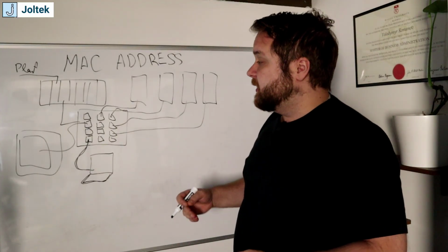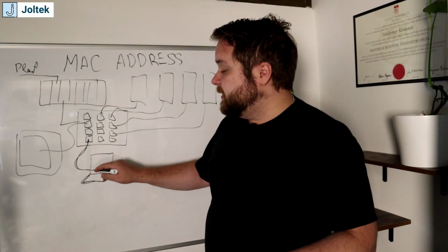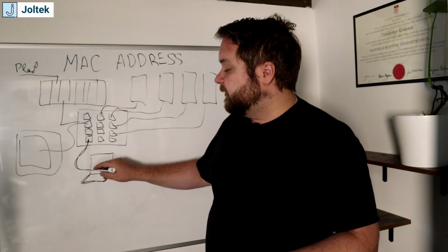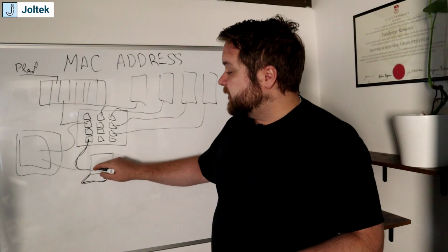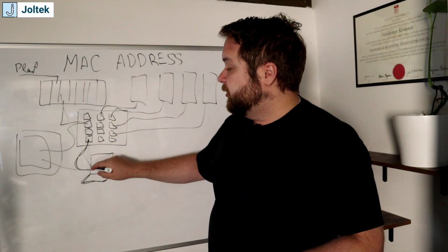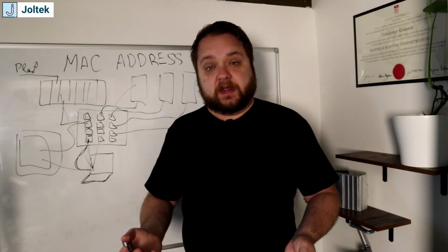And so the problem then on a live system, and even in a system that you've commissioned, is that you can easily make the mistake of, instead of, for example, setting the IP address of this HMI, you're going to set the IP address of this PLC, or the IP address of the switch, or an IP address of the VFD, right?